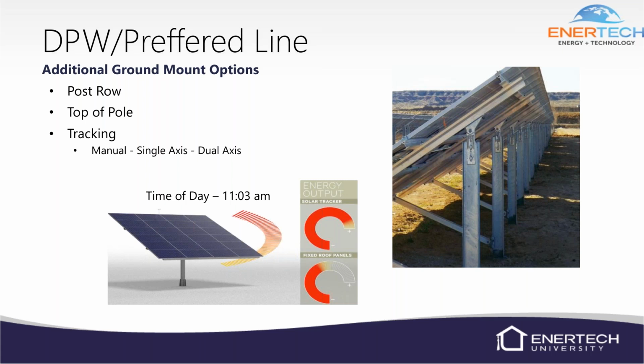So it would look at where the sun's at during the day and tilt and spin based on that. The problem with the tracking modules is that it's just like anything else. It's got a motor in there and there are other things that could fail. So cost-wise, it could be a little more costly for repairs, and sooner or later the motor will burn out on that tracking module.